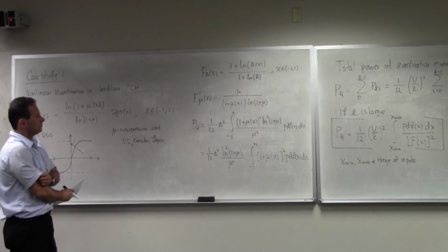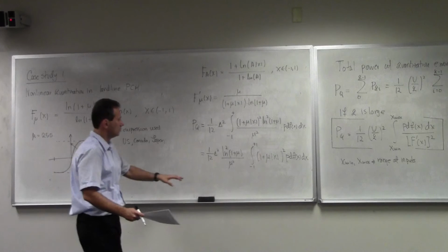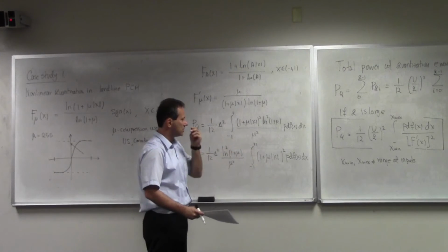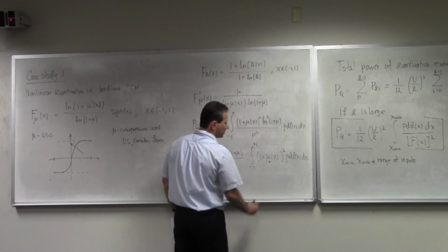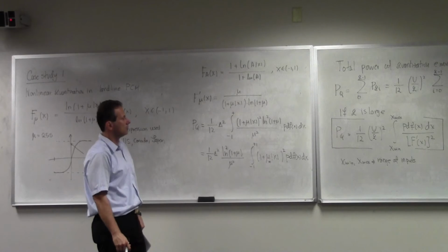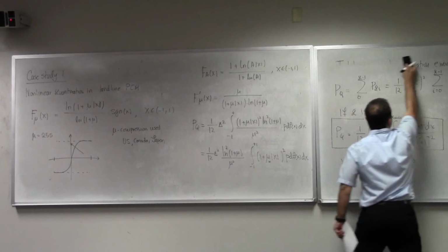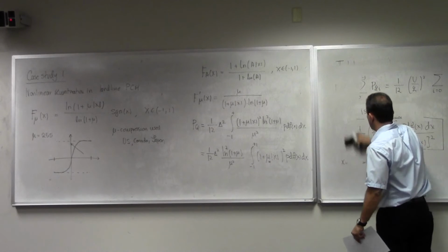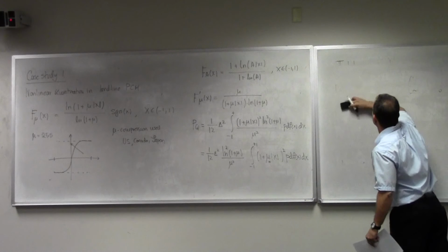So that's what the power of the quantization noise looks like. Now, this mu is an adjustable thing. It helps you decide how your compression looks, how much compression you have. It's not in the notes, but let me sketch what we are accomplishing here.